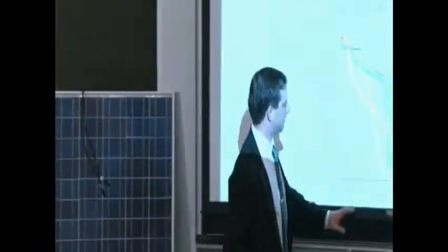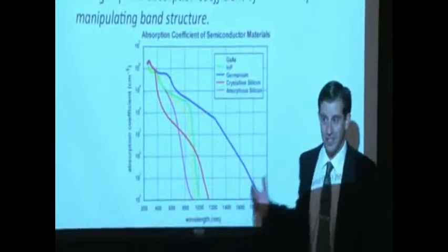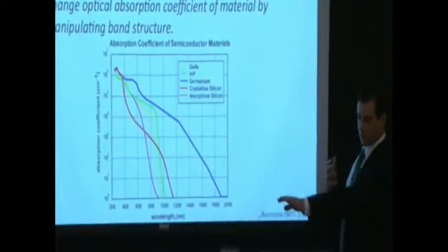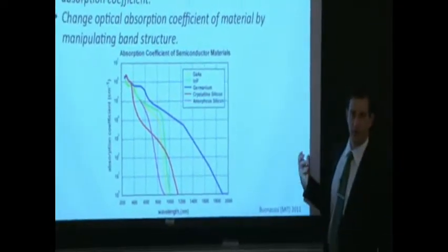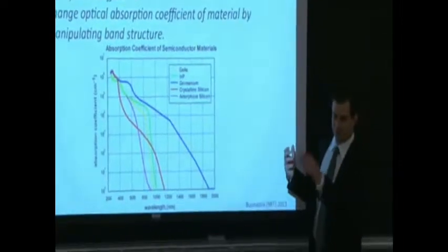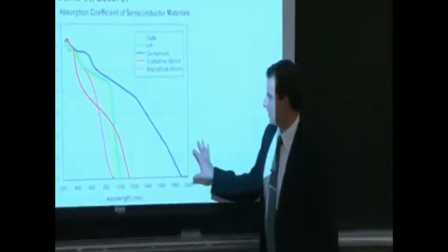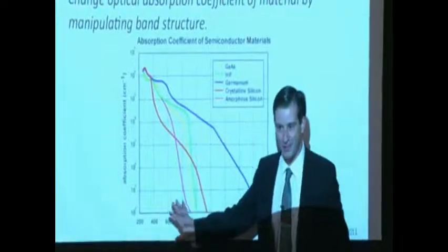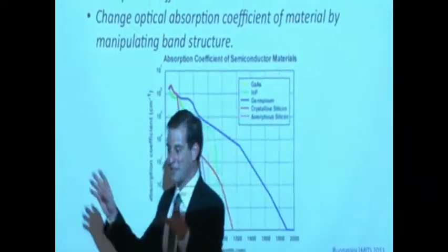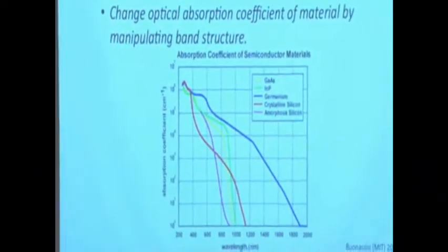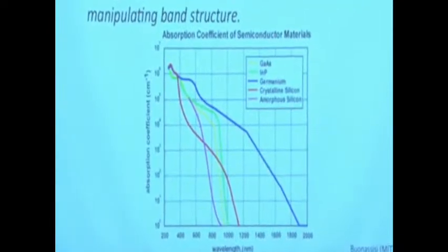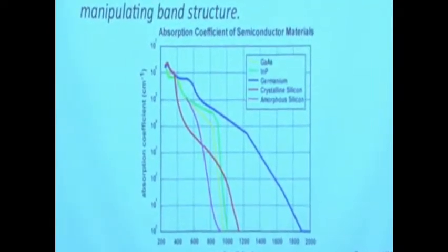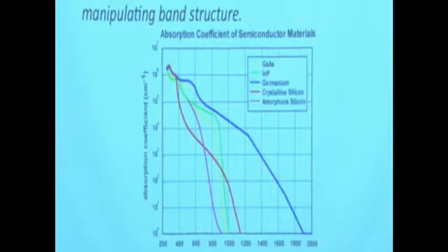If we can eliminate the longer wavelength stuff out here, which is heat, performance of most solar cells suffers when they get hot. And we'll learn why that is about 5 or 10 lectures from now. And so if we manage to do spectral upconverting or reflect that long wavelength light away from our device, we can improve performance there as well. That's another form of light management that doesn't necessarily involve light trapping.